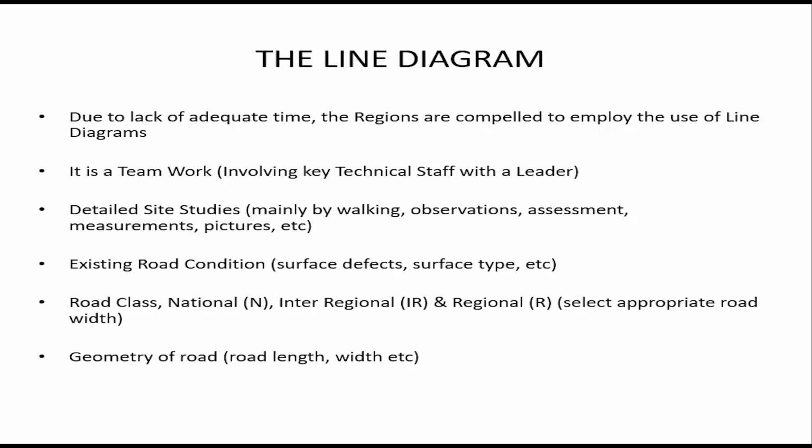You have to walk, observe, take pictures, and assess everything in detail. Some of the things you need to also check is the existing road condition. The road is sick, so you are going to diagnose it. So you need to know the existing road condition, like surface type, the defects, etc. That will help you diagnose the road properly.